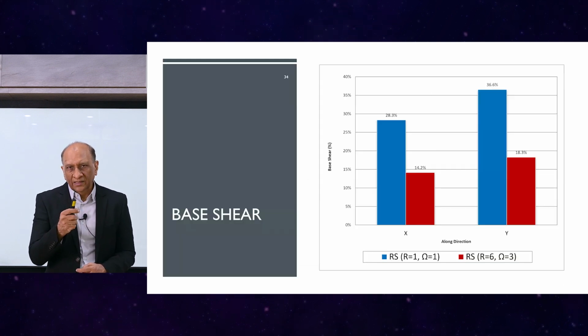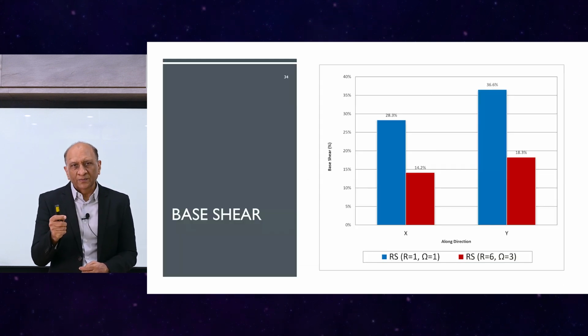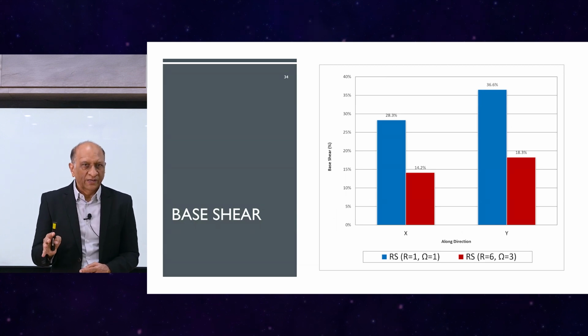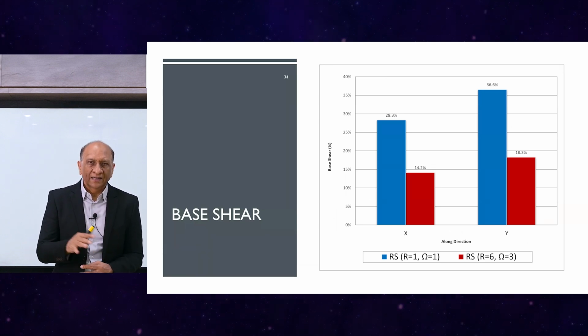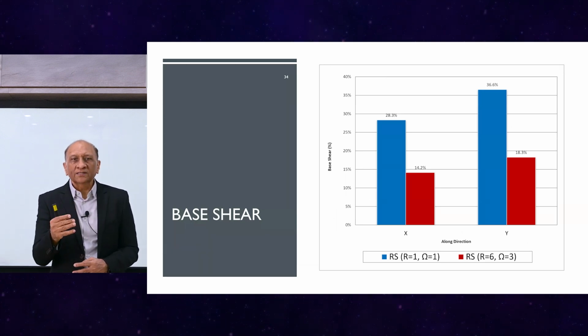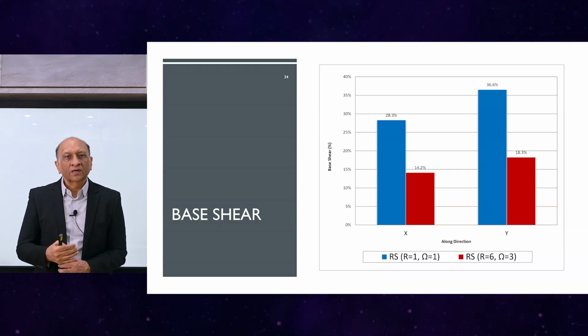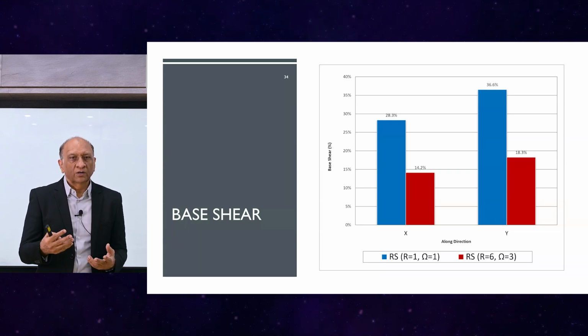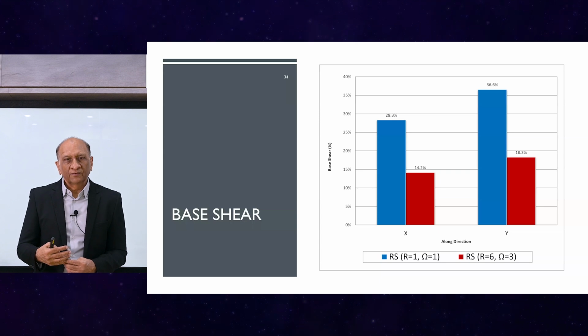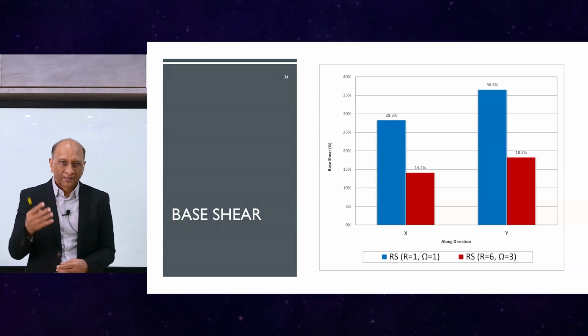And then the modal participation factors did not change much between the uncracked and the cracked section, as we expect. And you can see they are mostly, a very high percentage, in the first mode now. It's not like the previous one. A major portion of the structure is participating in the first mode, almost 70-75% in this case.